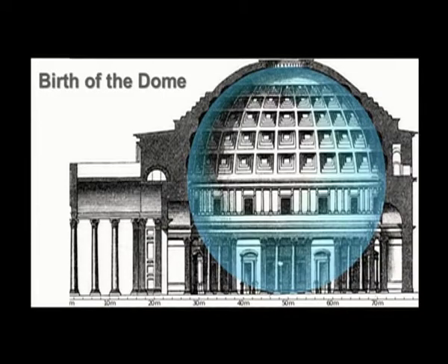Now, let us move on to the next interesting topic, which is a dome. This picture which you see here is the dome of a building called the Pantheon in Rome, where the height of dome architecture in Roman times is achieved. If you look clearly at the dome, in section all you see is an arch. This dome is very big, which you would have probably realized because of the scale which is given below. This dome diameter is more than 40 meters, and there is an oculus on top which is approximately 11 meters in diameter.